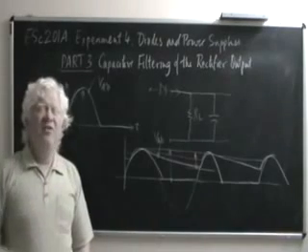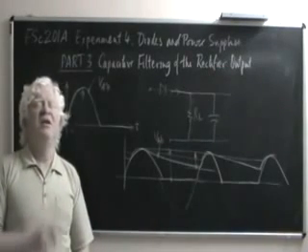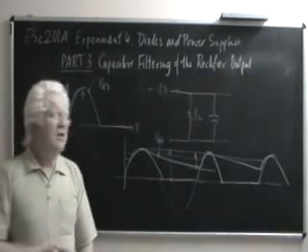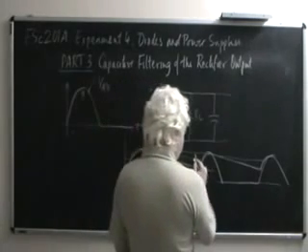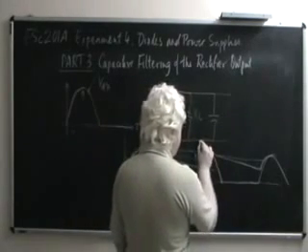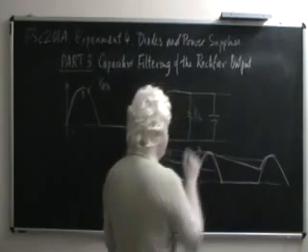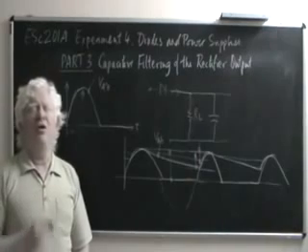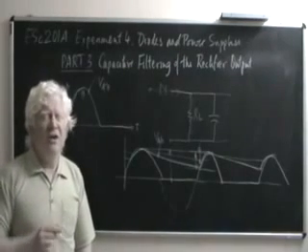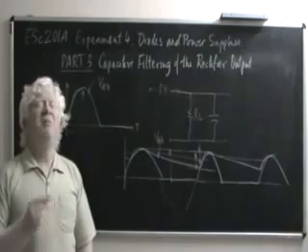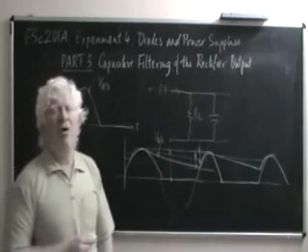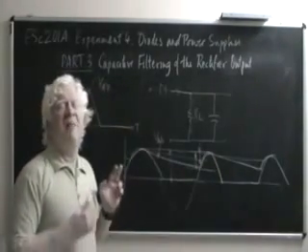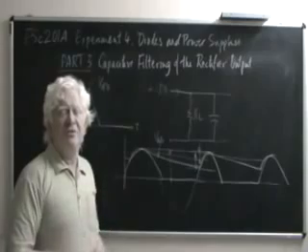At this stage, it is worthwhile to understand the advantage gained by using a full wave rectifier against a half wave rectifier. You see, the amount of peak to peak variation, I just said that this amount of variation depends upon R and C, or on the product of R and C, which is not incorrect. But it also depends on another thing. It depends upon the distance between the two times at which the capacitor gets an opportunity to charge.